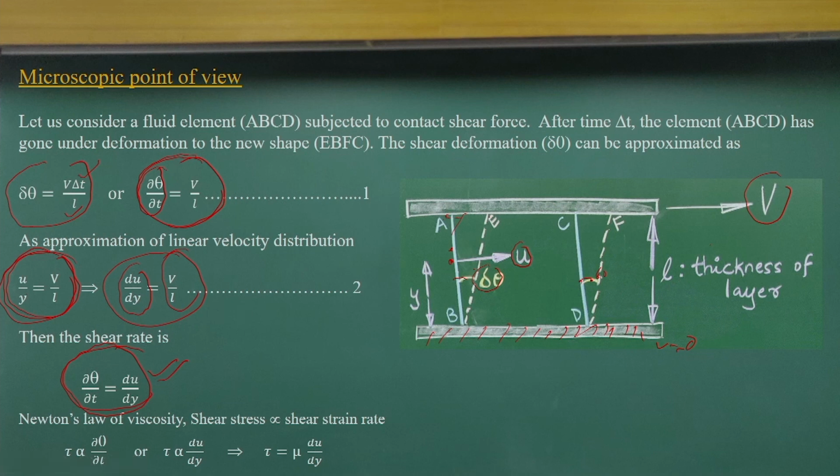So, now we are coming exactly to the solid mechanics concept, where stress is proportional to strain. But here we are talking about stress being proportional to the strain rate. That means the change of the shear strain with respect to time, not the absolute value of the shear strain. That is the basic difference between fluid mechanics and solid mechanics.